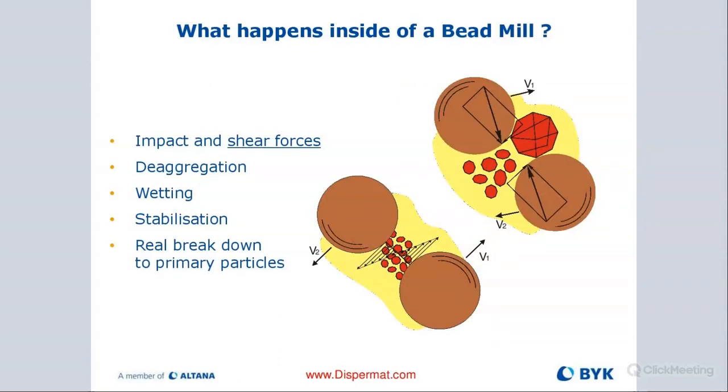Inside of a bead mill, we use media, beads, and there is a milling disc or a rotor, and as the rotor turns, it moves the beads. Usually, we recommend ceramic, either yttrium or cerium stabilized. They're very hard, and these beads get thrown around in your slurry, and that action causes these particles to shear.